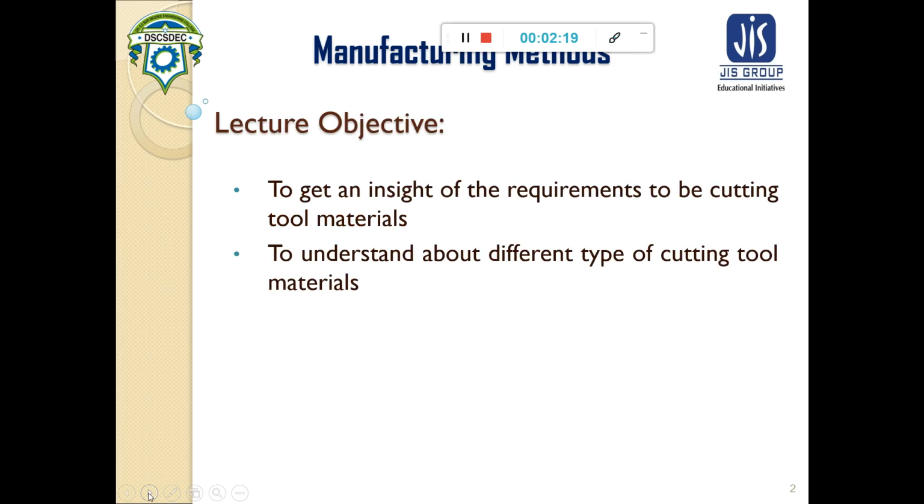The lecture objective of this lecture is to get an insight into the requirements to be a cutting tool material. To be a cutting tool there are certain requirements, and the first and foremost of them is that the cutting tool material should be hard enough to indent, to have an indentation inside the workpiece.